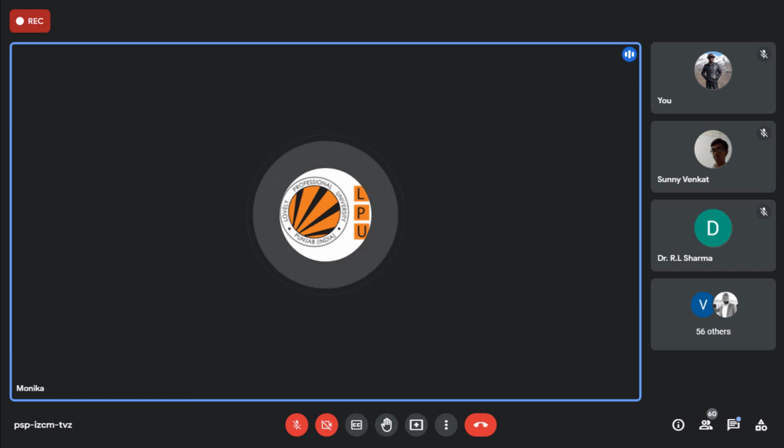Or another way I can say, to start another activity, you should have some lag. Now here the importance of lag came, because you are starting the project today. First activity, and after 3 days, the first activity of excavation is completed, and the same day you are starting another activity. You may not be prepared for the next activity, so problems may arise.